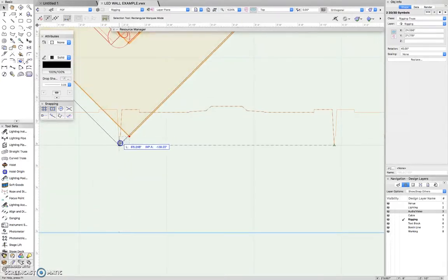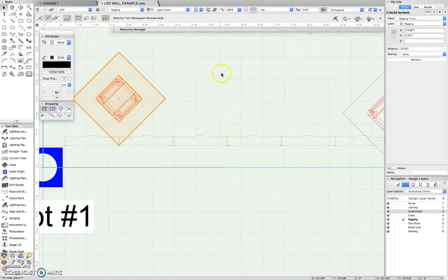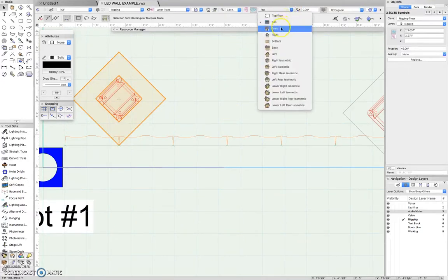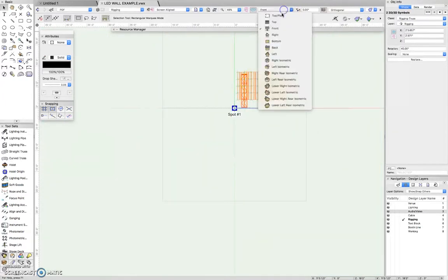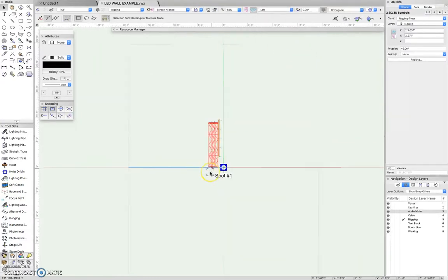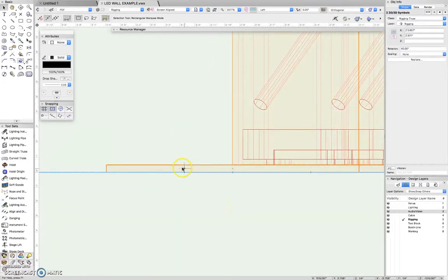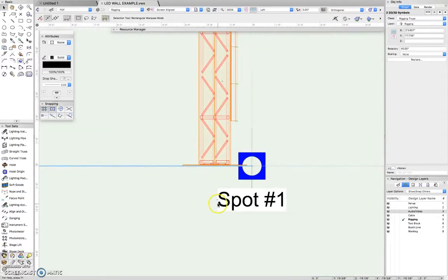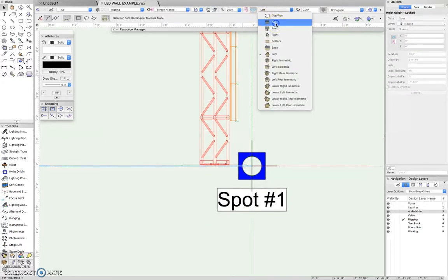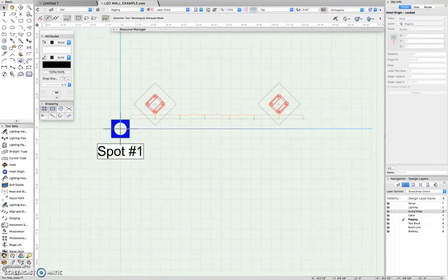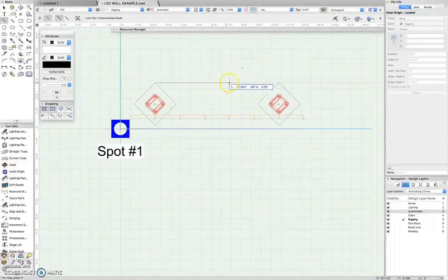Let's go ahead and line these guys up on the corner. And the other thing I'm going to do to line them up correctly is I'm going to go to the right or left side, just basically one of the sides. Because this is how I do it, I just don't like to eyeball things. So this is the edge of the base plate in the background, and this is the edge of the one that we just grabbed. So I'm going to drag this, and I'm going to snap it to that corner so that I know that both of my truss uprights are lined up perfectly. So if I hit the number 2 to create a line, and I click and I hold shift, it's going to touch just the corner because they are lined up exactly.